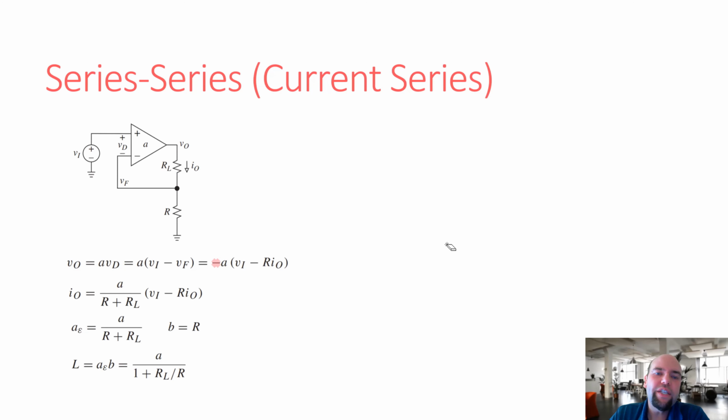But what we're going to have to do is, we know this is sampling the current, so we're eventually going to have to massage this equation into I out versus V in. If we just solve this for V out, V in, we're not going to get a full picture of what's going on here. Eventually we will get back to the same equations, but we're going to think this is doing something that it's not when we're doing this analysis. So just note that we've identified that we are sampling the current in this case, and so we eventually need to get the equation in the form of I out versus V in. So knowing that, let's jump in.